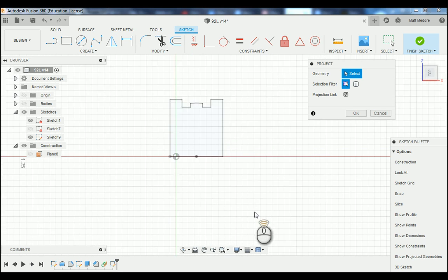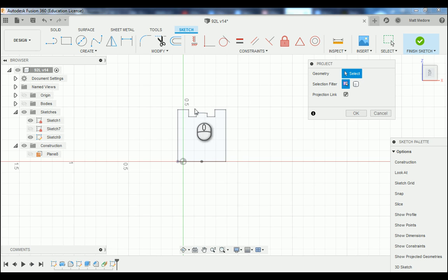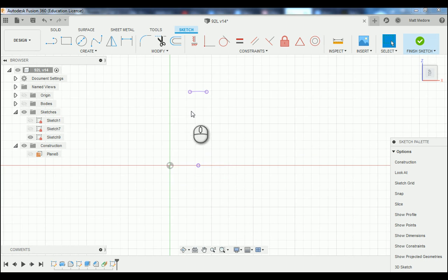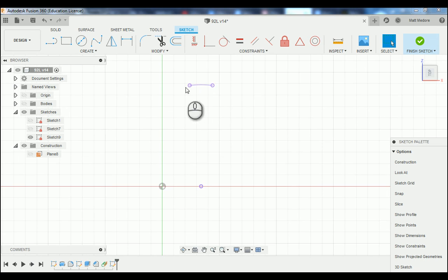The two components that we need out of our sketch here is this little arc, and then the center of this arc here, which is this point. Afterwards, we're going to press OK. And then we're going to turn sketch number 1 off, and you can actually see the geometry I chose. So we have this arc here, and then the center location of that arc.